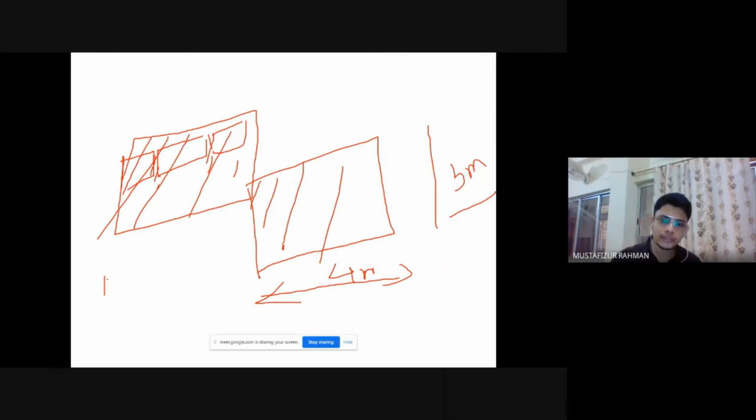We have to increase the materials required if the brick surface is uneven, with uneven mortar and joints. And then again, we have to increase it by 25 to 30% because of the shrinkage factor, because the fine aggregates will have voids and cement will go inside the fine aggregates and will shrink eventually. So we will have to consider a higher value.